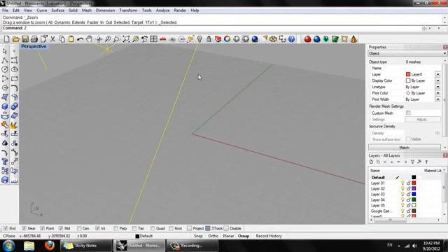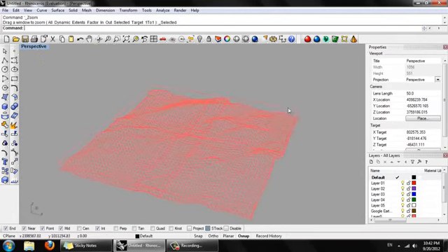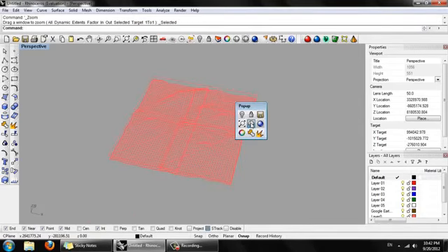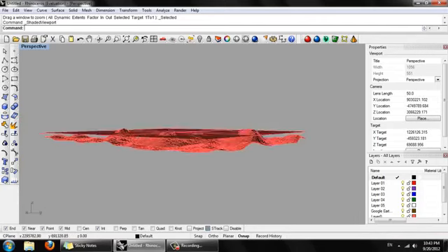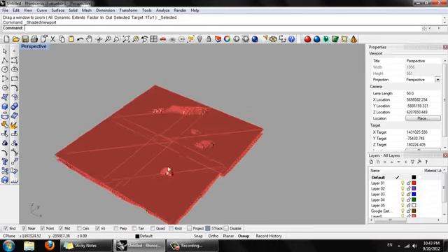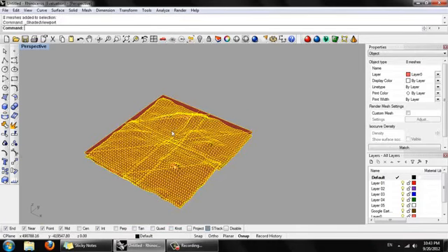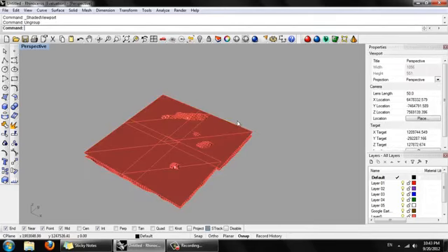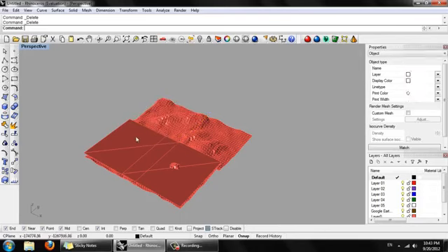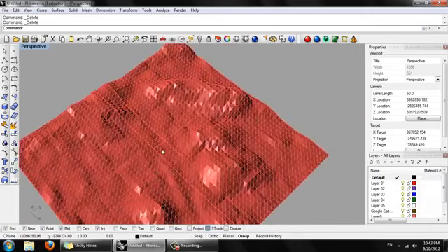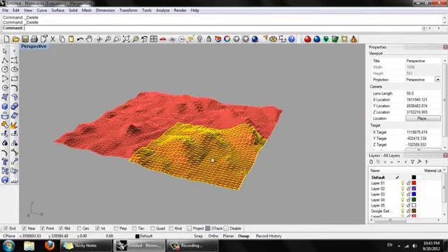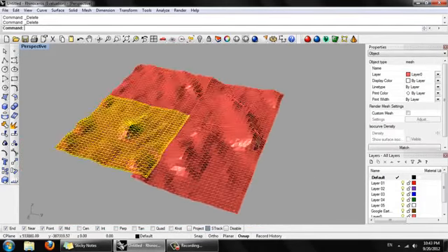We'll click on perspective and zoom out. So we can see that we've got these 4 overlapping patches. We go into shaded view. For some reason it's put these flat surfaces in as well. Select everything, right click, type ungroup, and delete these 4 surfaces. We now just have a mesh file from SketchUp.